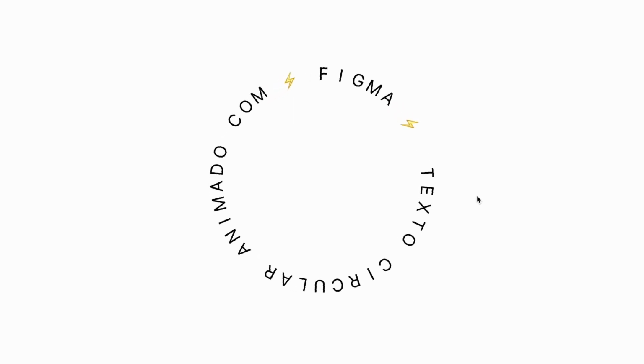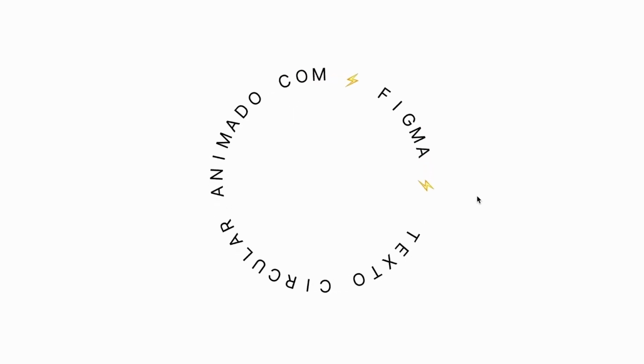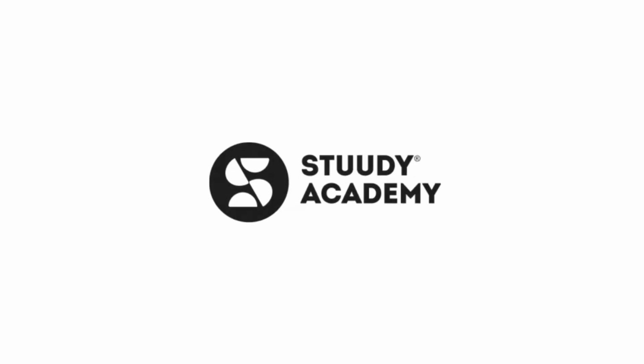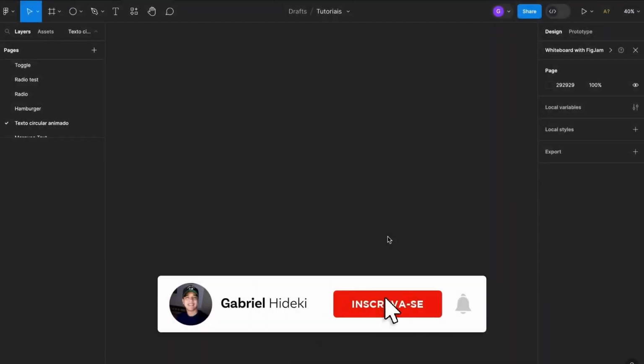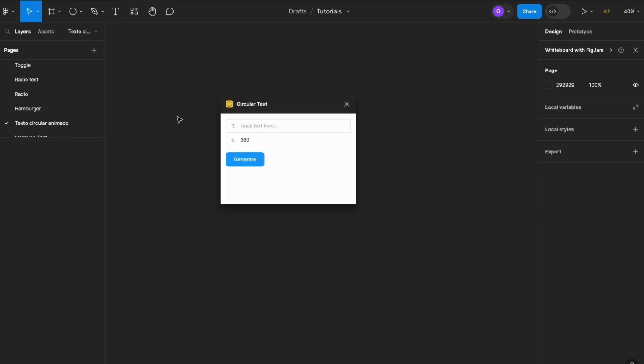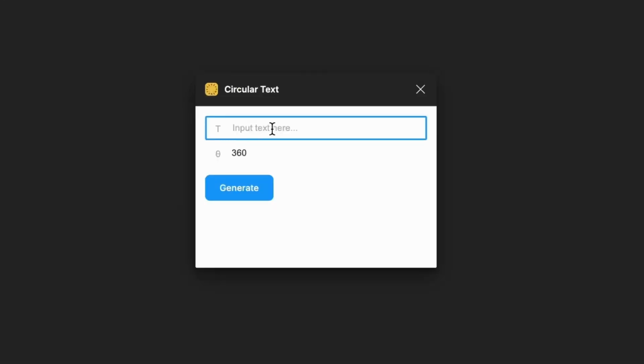In this video, we're going to learn how to create this animated circular text here in Figma. To create our circular text, we'll go to Resources and select a plugin called Circular Text. Let's click it. An input field will appear where we can apply our text.